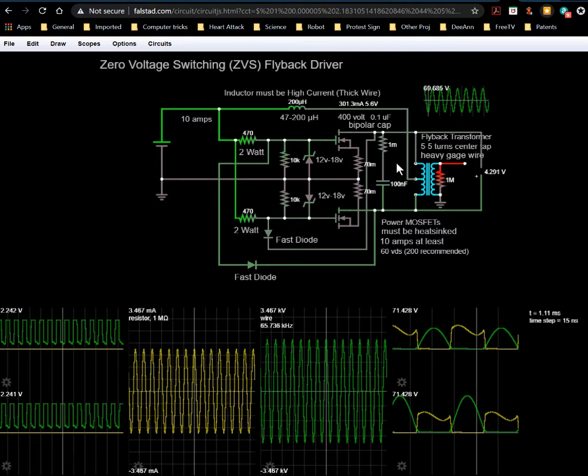You may have to put two capacitors in there, but you're never going to have more than one capacitor's worth of storage. That's what kind of sucks when you see one of those AC capacitors that may have a real high voltage rating, like 350 volts, but only 40 microfarads. It's actually an 80 microfarad capacitor because there are two of them in there, but you can only use one of them at any one time because they're connected.